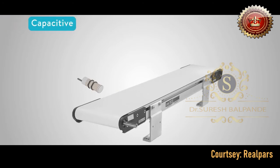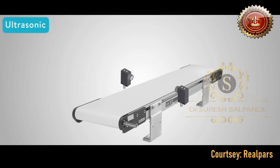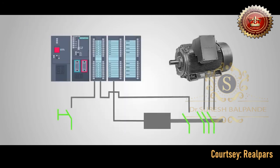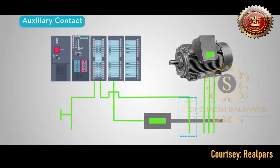Capacitive proximity sensors are like a proximity sensor, but for detecting non-conductive materials. They are very sensitive to contamination, and historically have not been very dependable. Ultrasonic proximity detectors detect solid objects using high-frequency sound, but are very susceptible to environmental conditions and dirt. We don't use them often, but they can solve sensing problems nothing else can. An auxiliary contact is a part of a relay. These tell us when whatever is controlling the relay has turned it on or off.